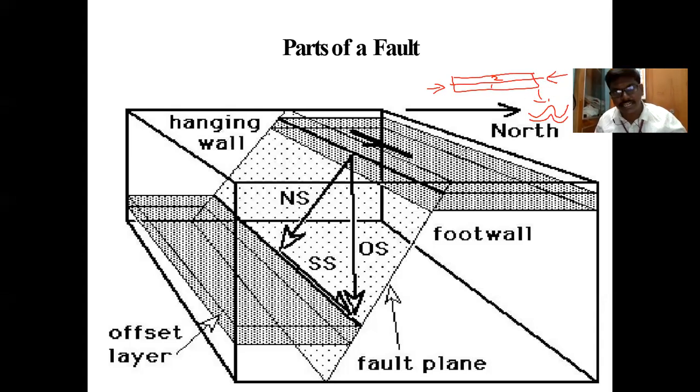Similarly, if these tectonic forces are not sufficient, or if the tectonic forces exceed some limit, that is the shearing force. Because of that, faulting of the rock bed happens, right? That is what a fault fracture is, which you will see whenever faulting of a rock bed happens. The simple red line which I have drawn is our fault plane, which is the first part, because of which it will divide the rock strata into two halves. One half may be moving downwards and another may be moving upwards, right?